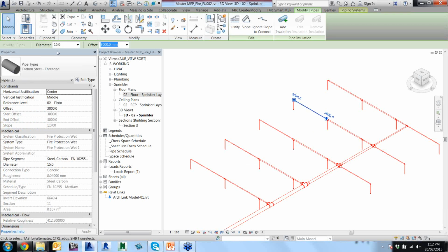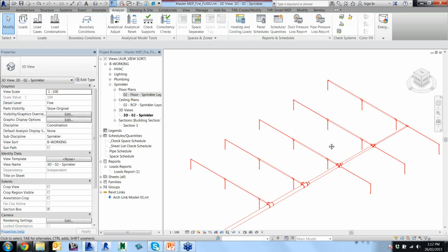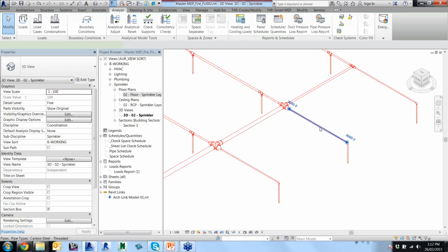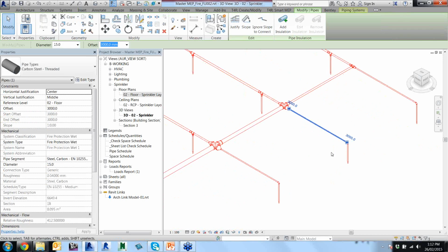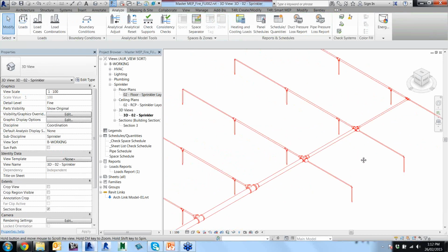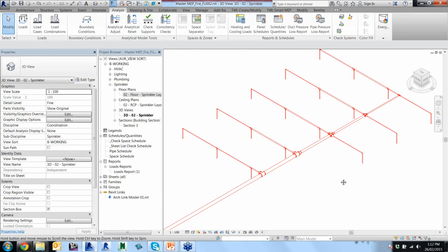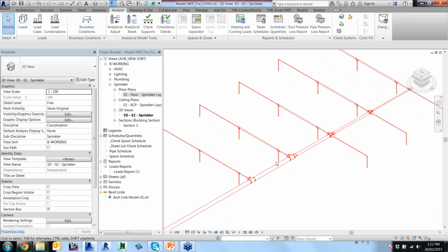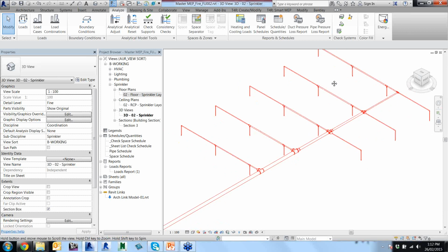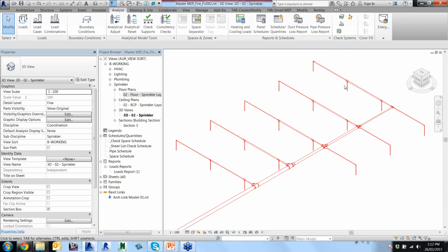And then the rest there should be fine sitting at 15 there. Okay. And on this side we should be okay as well because it should be 15. These are only feeding 1. Okay. So effectively, look, a bit of manual manipulation there, but you can see how quick it is because everything stays connected and the routing preferences will put in the fittings that you need as you change and alter sizes. Effectively, that's a way that you can quickly size your pipes when you're laying out a fire network.